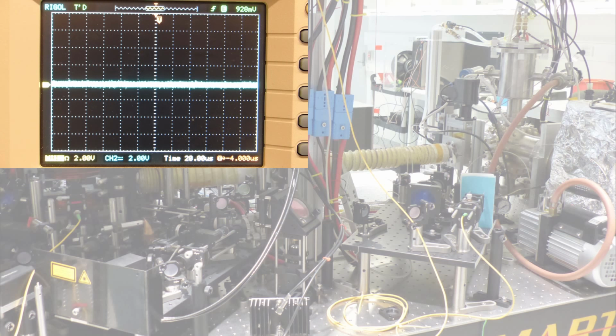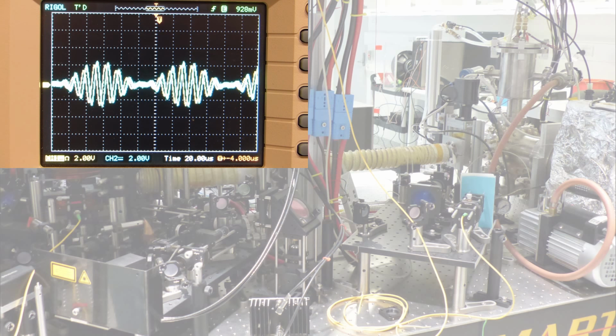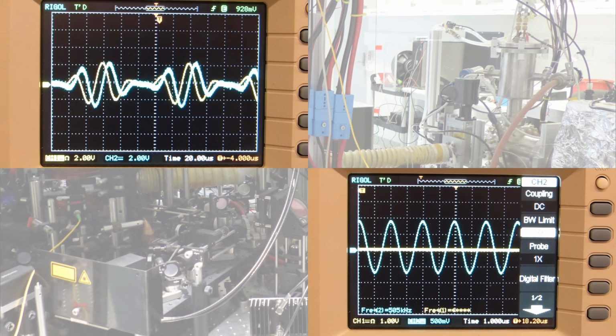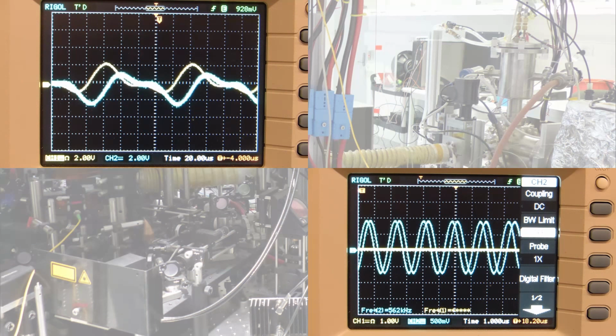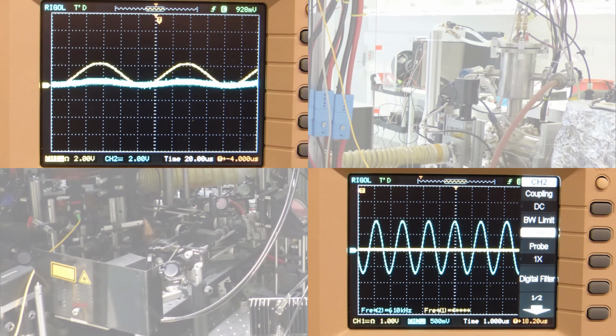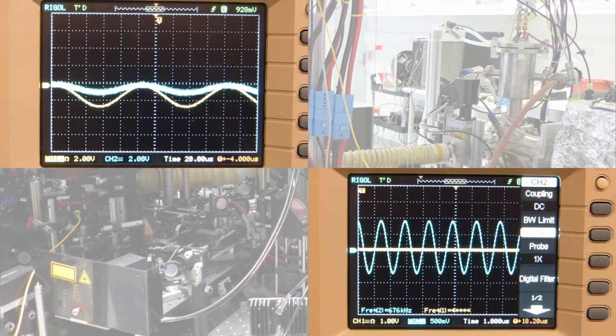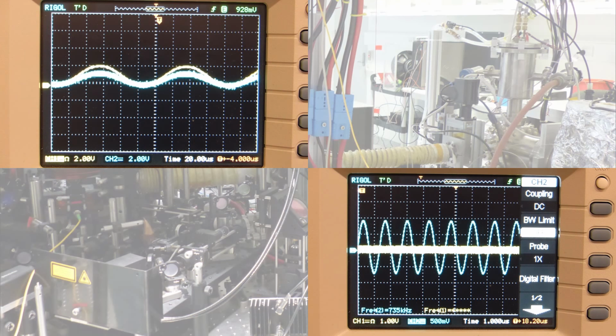So we've got to show our system is actually working. These 4 videos will show you the operational ability of our FPGA circuit and differential amplifier. In the bottom right, you can see an external frequency in the blue being mixed by our internal IQ module, resulting in the yellow output. As we increase the frequency, it'll come towards 1 MHz and mix appropriately and then fall back off.